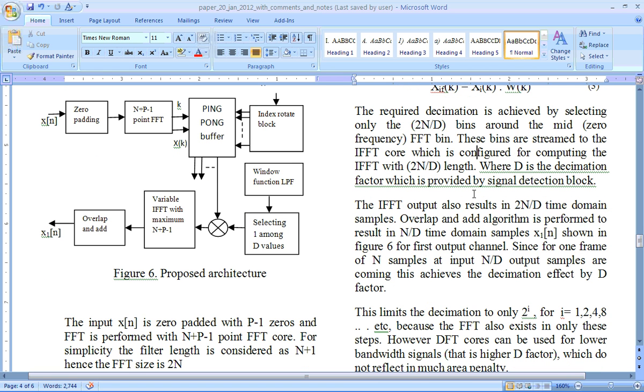This technique is not directly discussed anywhere in the literature. I wondered initially why people have not tried this. But when I see the characteristics, for example the decimated signal spectrum, it's coming out very fine. Not only for a single signal, even for simulated true digital signals, BPSK and QPSK, I have verified.